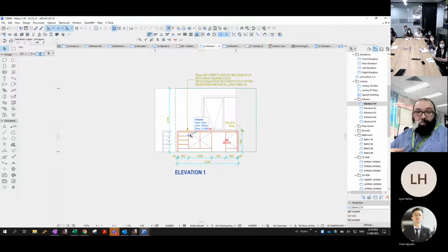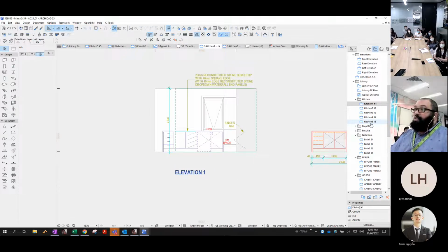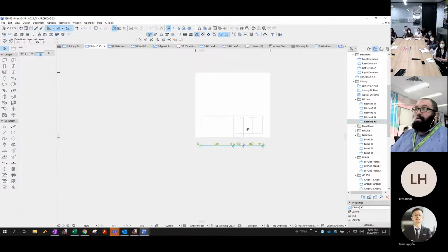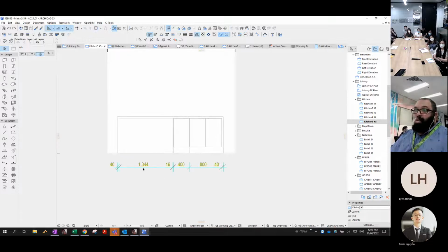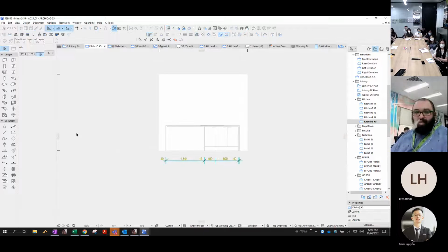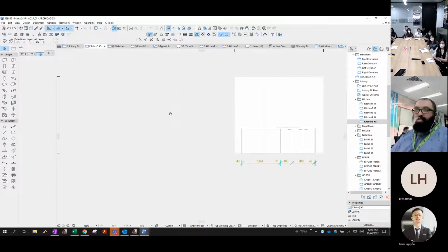You then have to go in and amend the plans because of the 2D elevations. If I show you elevation 5, I've moved it across. My dimensions have moved across. With any 2D line work that we've added to it, like the door openings or the labels, you just select it and drag it across very quickly. This makes amending joinery so much quicker and so seamless. It also ensures we don't have any errors where our floor plan doesn't match the internal elevation.